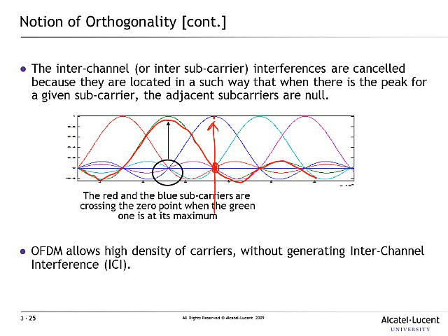So this is what I meant by the fact that we can pack our subcarriers even closer together using this idea, because we make sure that the tails of a sinc function have a zero value at all points at which the adjacent subcarriers have maximum value. Mathematically you can explain it this way. So one subcarrier is not going to affect the adjacent subcarrier, and we can get rid of this interchannel interference.